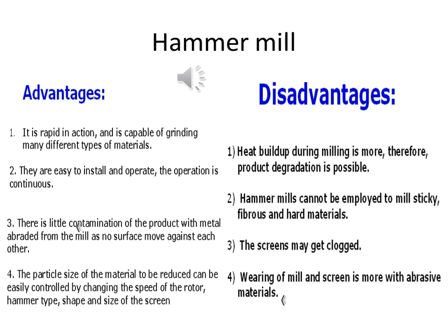The particle size of the material to be reduced can be easily controlled by changing the speed of the motor or rotor, the hammer type, and the shape and size of the screen.